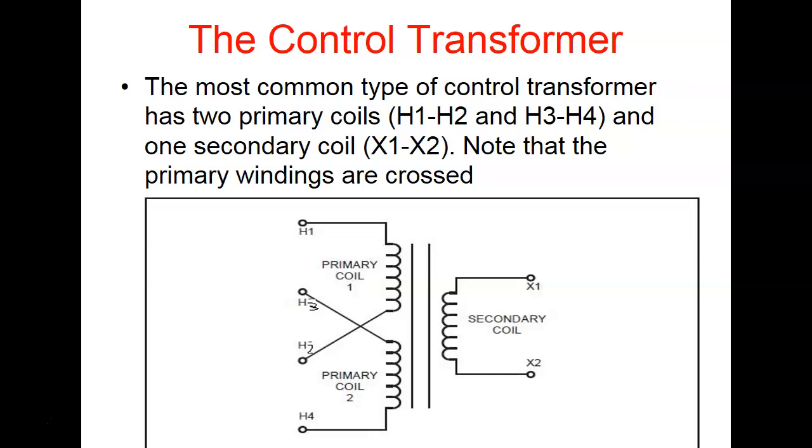So now the current's divided between 2 windings, right? You understand? So how would we hook these in parallel? Well, you want these two connected together, so tops to tops and bottoms to bottoms. So I want to put a jumper between H1 and H3, and a jumper across H2 and H4, excuse me. So what I've done is I've wired my primary like this.